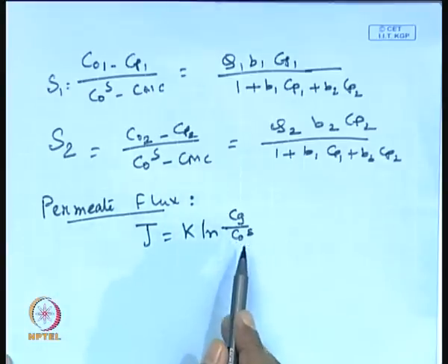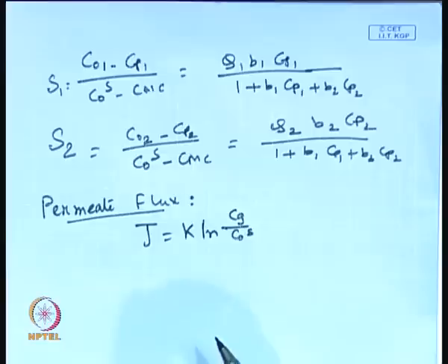And you can find out the value of Cg. You can conduct steady state experiments with different concentrations of the feed surfactant and measure the steady state permeate flux, and then plot the steady state permeate flux as a function of feed concentration on a semi-log plot. Okay. Then you will get a straight line, and if you extrapolate the straight line, the point where it cuts the x axis will give you the gel layer concentration. The same way we measured the gel layer concentration earlier in the case of protein or polymeric solutes.